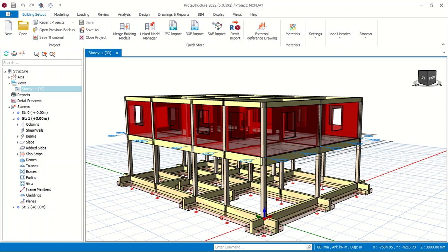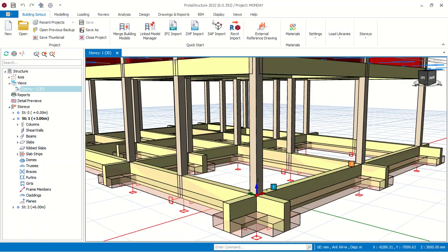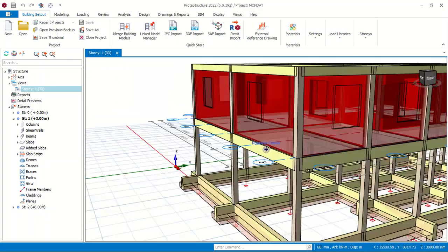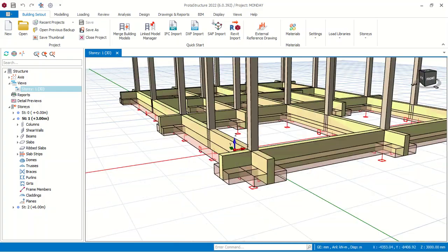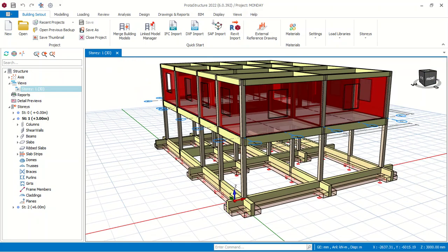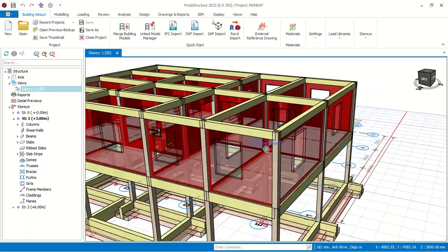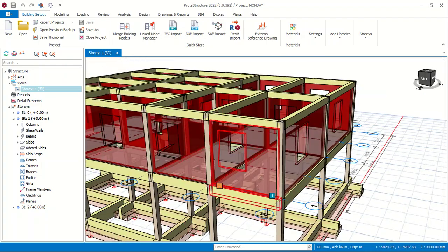What I actually used here is strip foundation, so you can see the strip beam and the strip itself. Our design is for a particular structure in Ikota in Lagos, and the area is a bit swampy, so this is the best for this location. The reddish color is the wall load that has been applied, and you can see an opening there. That opening shows that I had to deduct the window for each of these walls, so the wall load can be reduced. By the time this area is calculated out, the entire load will be reduced.